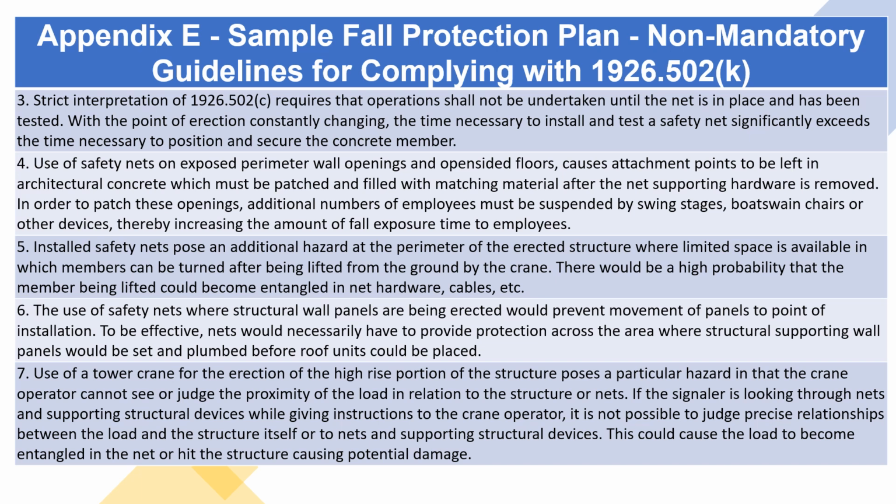4. Use of safety nets on exposed perimeter wall openings and open-sided floors causes attachment points to be left in architectural concrete, which must be patched and filled with matching material after the net supporting hardware is removed. In order to patch these openings, additional numbers of employees must be suspended by swing stages, bosun chairs, or other devices, thereby increasing the amount of fall exposure time to employees.